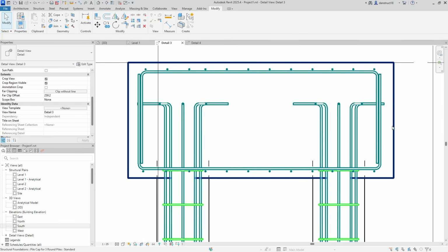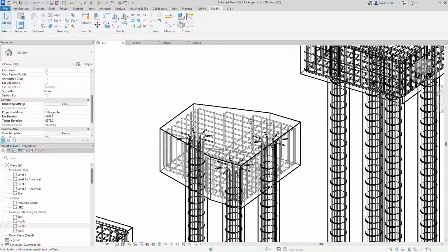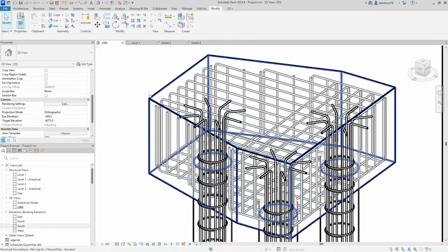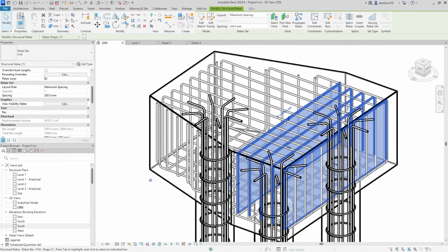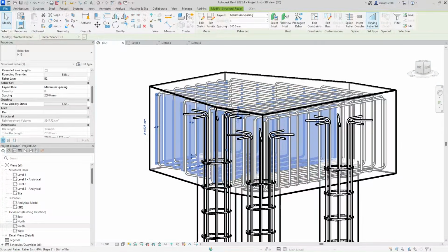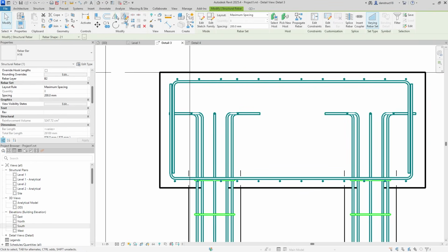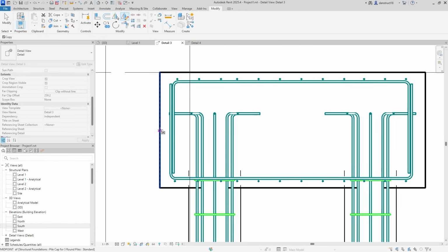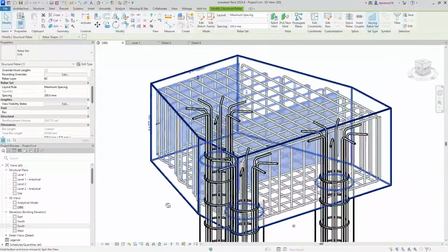All right, good. So we can also check in the 3D view that we've mirrored everything. So we can see we've mirrored everything. We just forgot to select this particular one because we didn't have a section for it. So we need to go ahead and do this for this as well. So I'm just going to select the bar in question, this particular one here. So I've selected it. I can come back here into detail 3. Even if you can't see it, we can still use this plane to mirror. So you see it selected here. I'll click here on mirror draw axis, come here and find the center, click here, there we go. If I come to the 3D view, you can see we've been able to place it in the right direction.